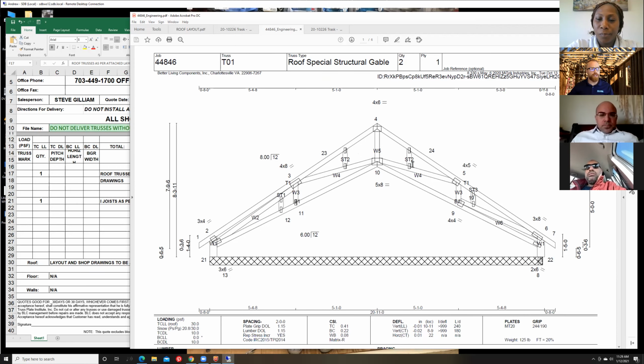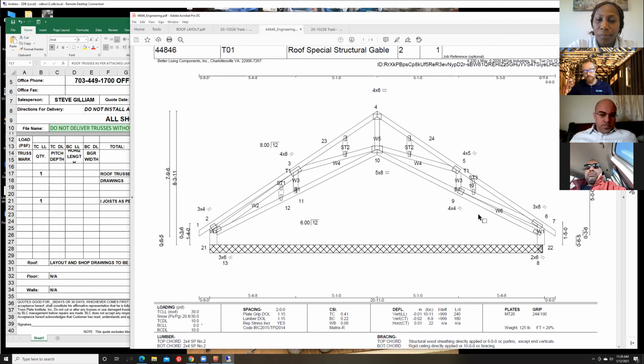So going to the next truss, when verifying it, of course, going to Salima's reference sheet, we need to look at the span all the way across and heel heights and everything like that to make sure it works. We need to look at the CDs to make sure that the inside pitch that is proposed to the clients is matching what the truss company can do. So it's an 8-on-12 on the outside and a 6-on-12 on the inside. Make sure that those are correct and will work.